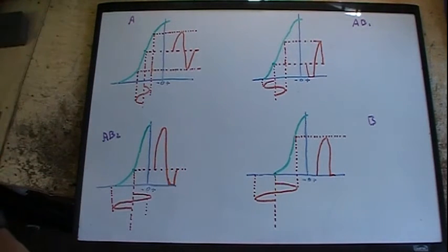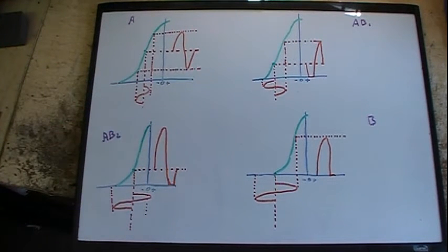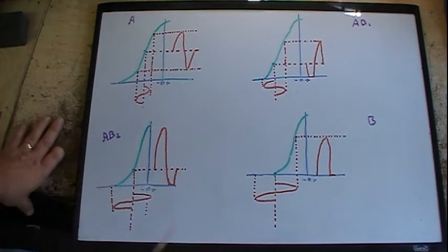But then iron got expensive, the Depression came on, so some other means had to be figured out. And for those companies that still wanted to keep using Class B and didn't want to pay for the transformers, they had to do some elaborate circuit work on the first audio or the input audio into that push-pull, and they either pulled current off the plate circuit, which meant you didn't have a coupling cap, and you can do that.